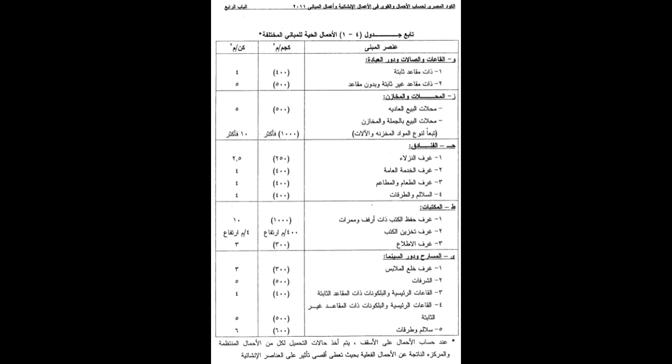For halls like cinema, exhibitions, mosques, churches, the code for halls with fixed seatings, having chairs fixed in place, is 400 kilogram per square meter.